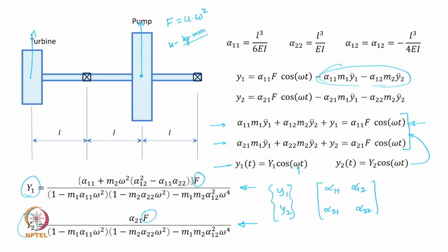So, then you will have to figure out which stages are having larger mass, some of the discs which are smaller in terms of its mass or weight can be ignored for the sake of getting the first cut idea or guess on the natural frequency of the system. Okay. Now, that is how you do it for the lateral vibration problems.